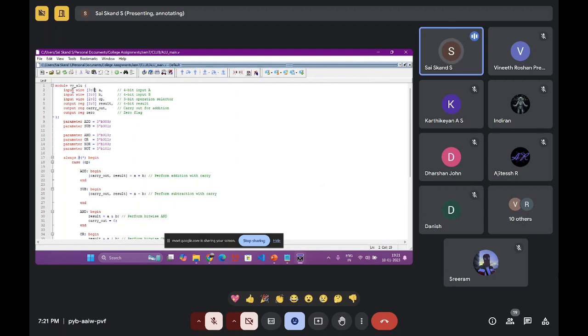From input, you can tell that it's an input data. And then wire, what does wire mean? It's a type, data that is not stored. It won't get stored because it's coming from outside the block. It keeps changing, it's from another source, so it's not stored inside the block. So we put wire. I guess it's all clear.